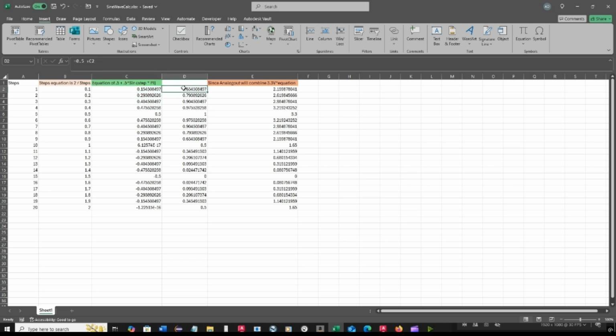Right as we get over here, this was the final answer. And you'll see on the code talk, you're like, well, how come I'm putting in the calculator? How come we're getting these numbers right here? Why is it 0.5? Well, the reason why it's 0.5, and this took me hours, I had to think about it too, is the computer will times it by 3.3. That's 3.3 volts. Now it makes sense.